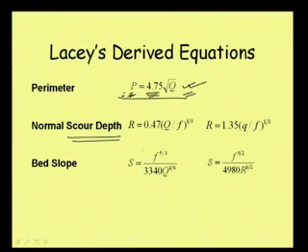Similarly, the scour depth is also used for design of many hydraulic structures, that is, what will be the R. That R we are calculating indirectly from this formula, that is Q, F, and these are coming. This is in terms of total discharge, this is in terms of unit discharge, and by using these we are getting R, because this is in regime condition.